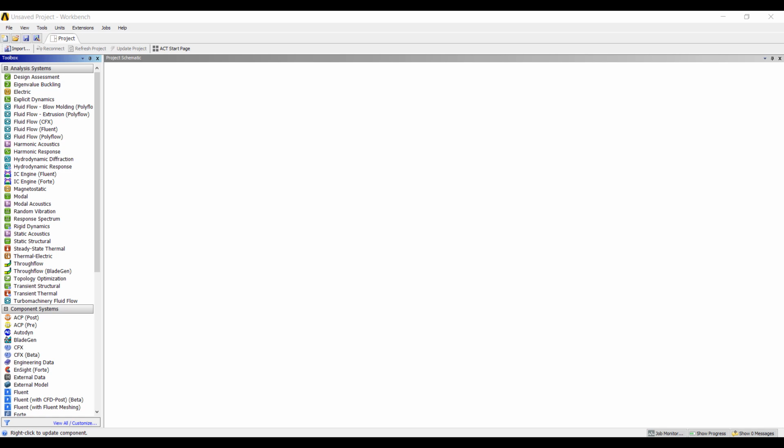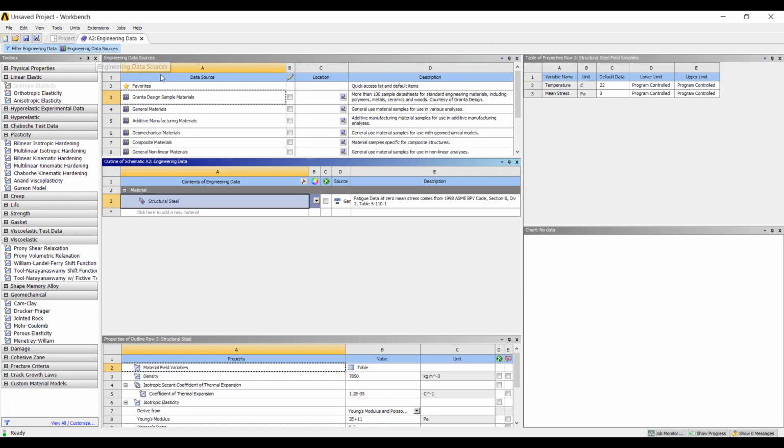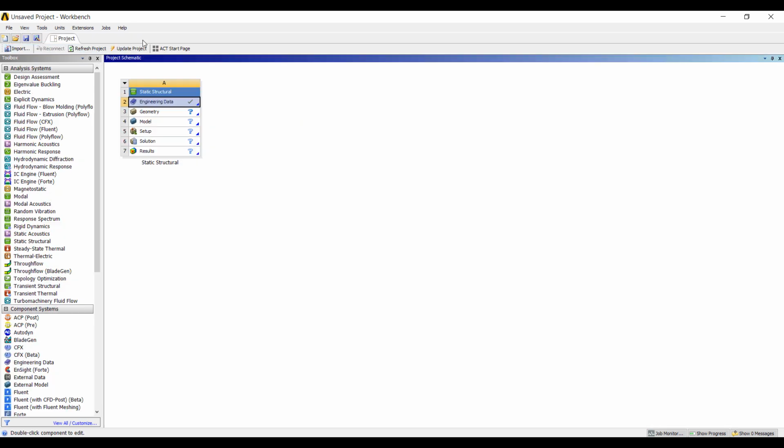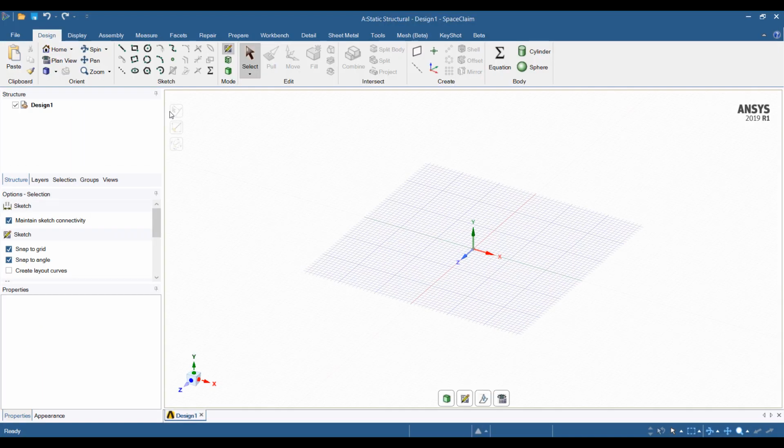Today I'll be doing a demonstration of a press fit or shrink fit problem. Press fit problems involve squeezing typically a soft material into a hard material. So we're going to go with polyethylene here and structural steel. This is often used to hold a piece of material in place and give it some support. And simulating this effectively requires a nonlinear contact simulation. So I'm going to give a quick example of how that's done in ANSYS Workbench.